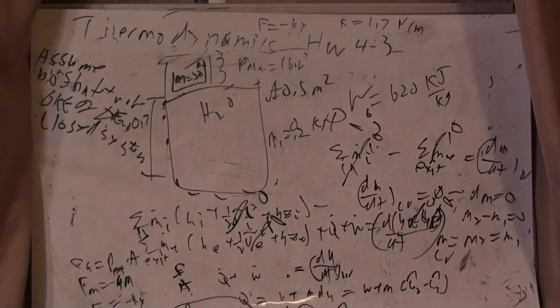So you have this net force that you'd have to account for. You could back calculate what the pressure would be. So now you have a pressure. Now you have a specific volume. Bring that together and you can get your temperatures and your internal energies. You have your work, and then you can get your heat transfer.